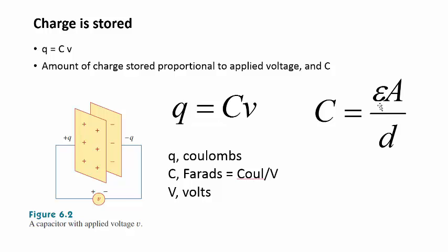So permittivity is a material property. This material that's sandwiched in between the plates, even air will make a capacitor, but in general it's something like Mylar, plastic, paper, or an electrolytic, which is more like a gel. And it has a material property, a permittivity associated with it, which you can look up in tables of material properties. Permittivity is in farads per meter.